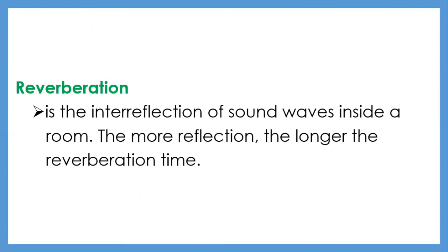What I mean is that if there is continuous sound, background noise caused by inter-reflection builds up to a steady level called the reverberant field. Reverberation is a very important acoustic characteristic that influences an occupant's perception of a room, as shown in table 11.10.